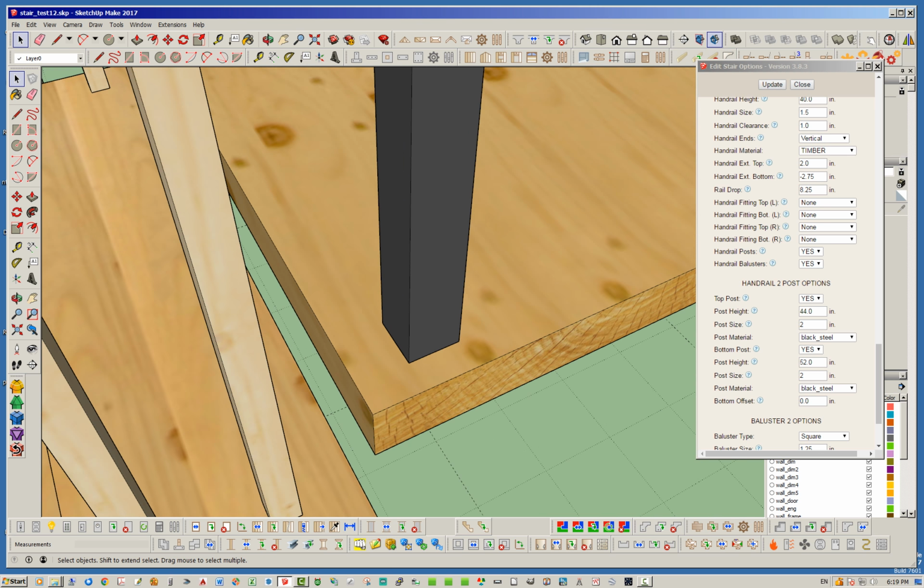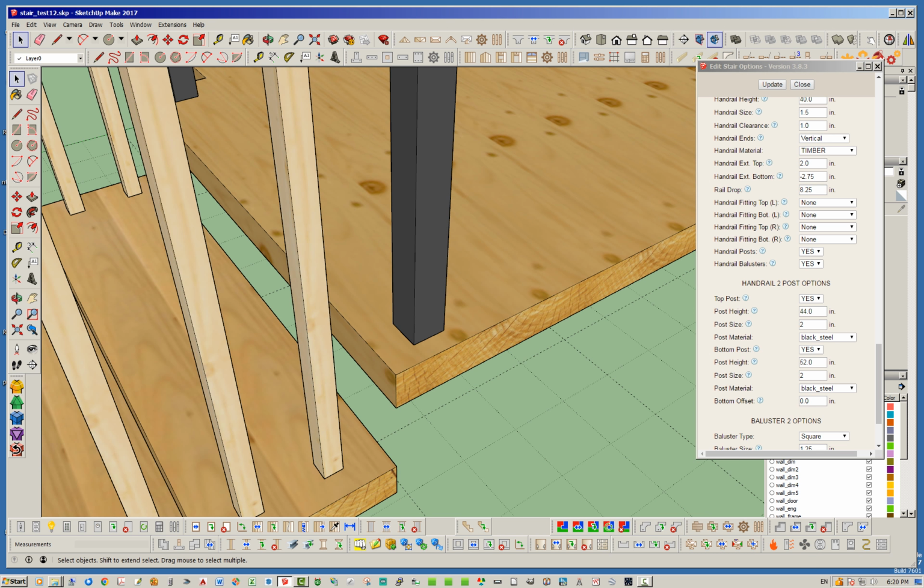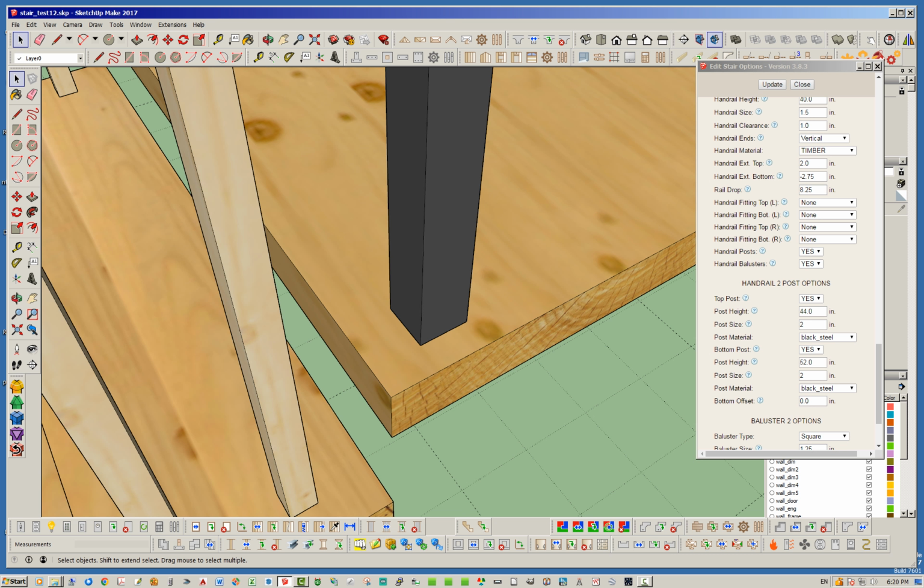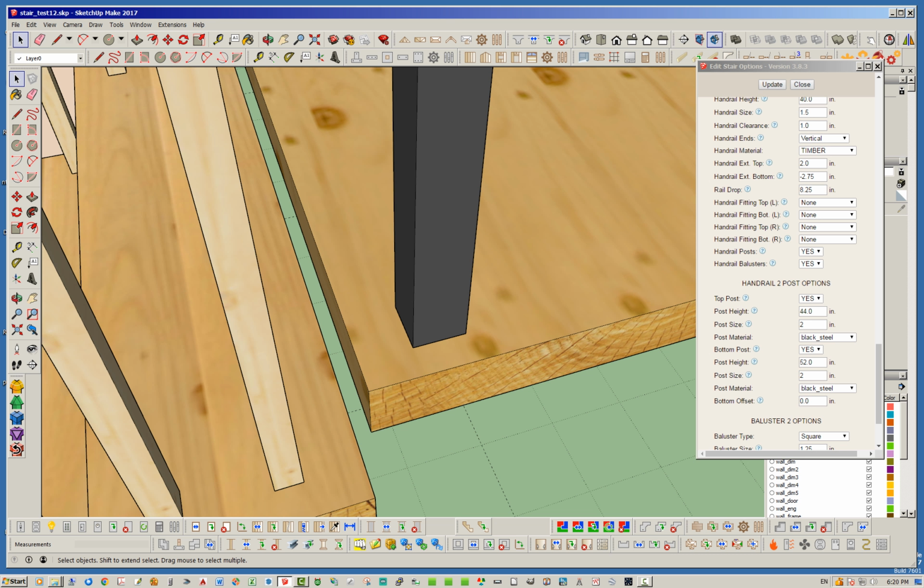Okay, and you'll notice on the different literature for these cable railing systems and glass railing systems, at least what I've noticed is they usually have like a 1 inch little base. And I don't show that here, by the way. I just show the post, but they usually have a flange welded to the post, which you can then connect into your tread here. So that usually has, I think, a 4x4 base. I'm not entirely sure, but anyways, the point is they tell you, in the literature, you want to stay 1 inch away from the edge. And so in order to do that, that means we need to be 2 inches.